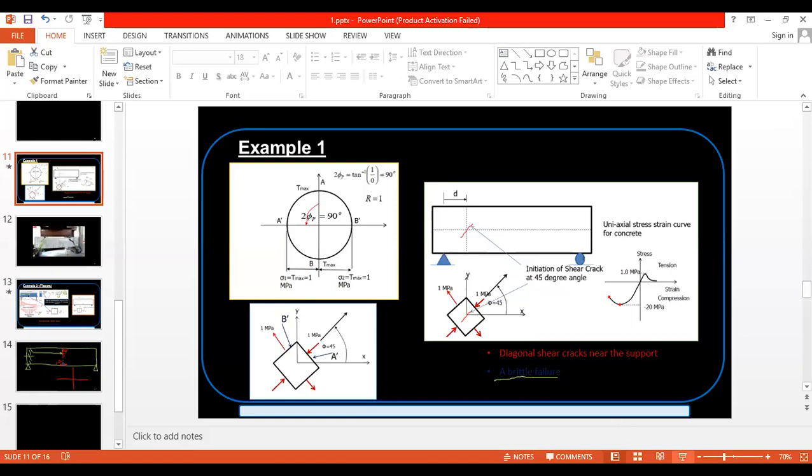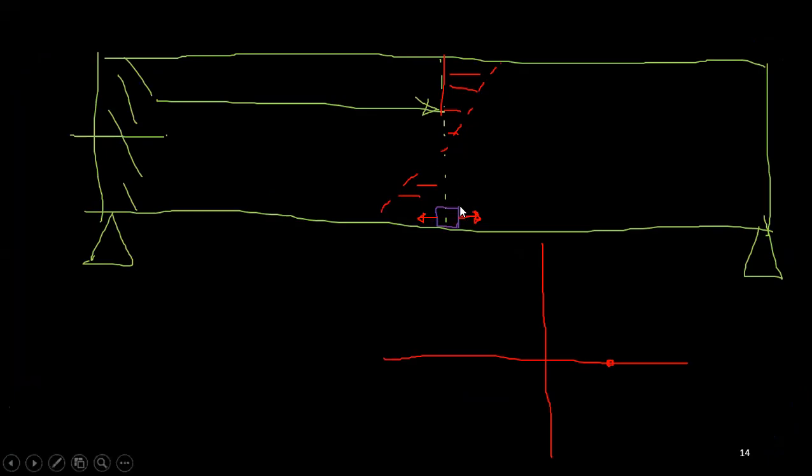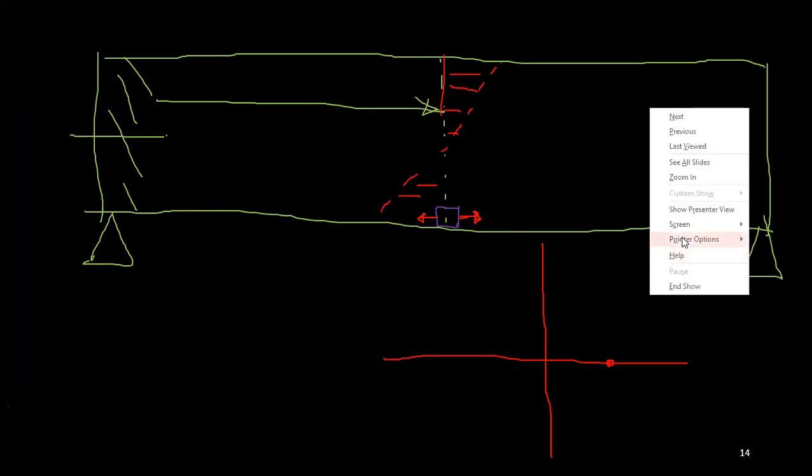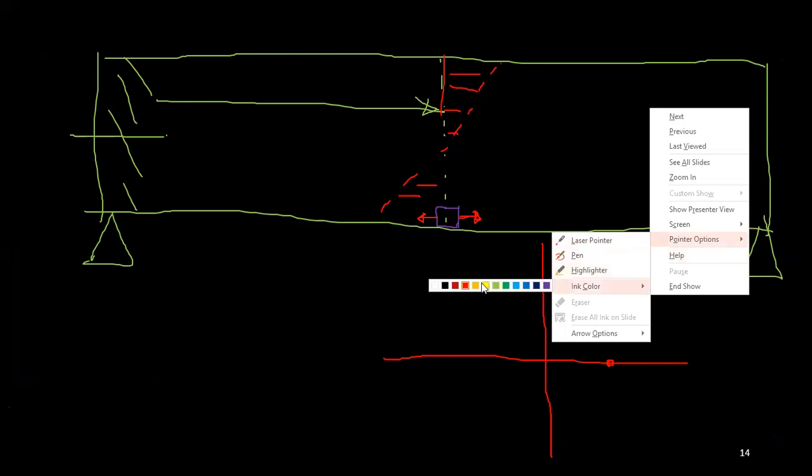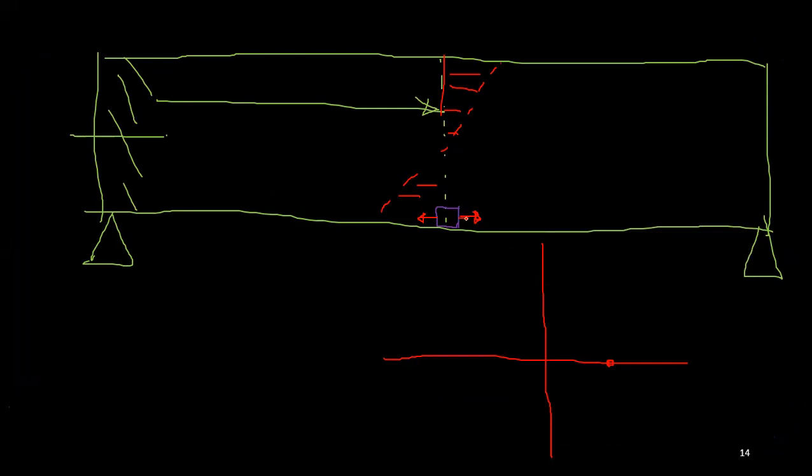So we were in here, right? In the Mohr circle, this element has tension and zero shear. And it's 90 degrees, right? You take this 90 degrees in this element, so that is 180 degrees in the Mohr circle. We have zero normal stress and zero shear stress. That brings you to the origin. So you can draw it like this.